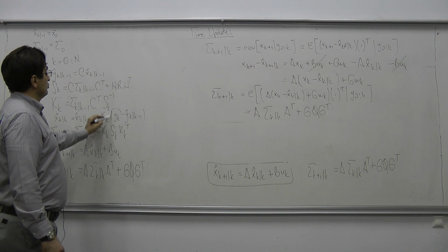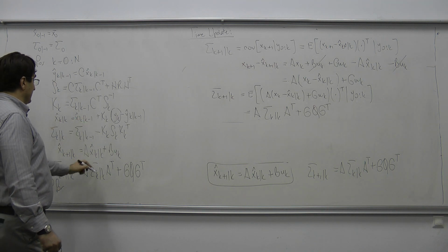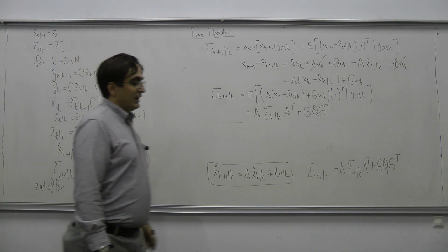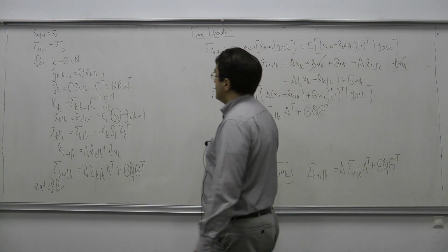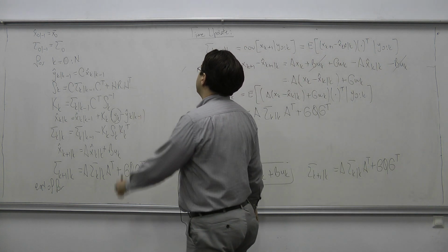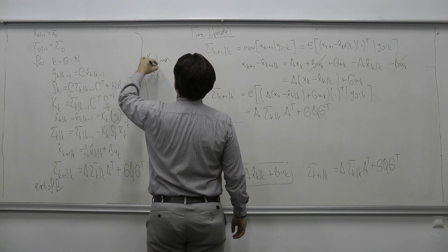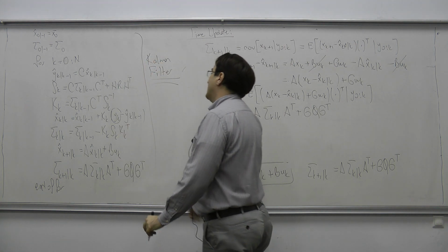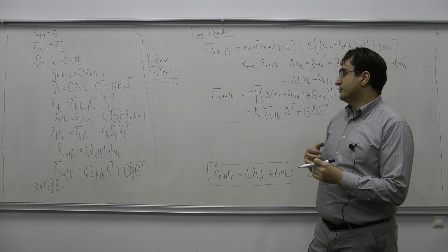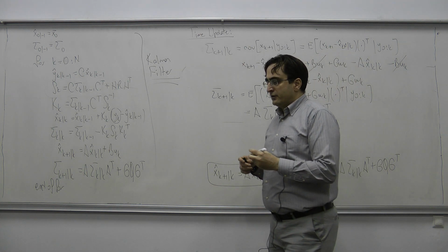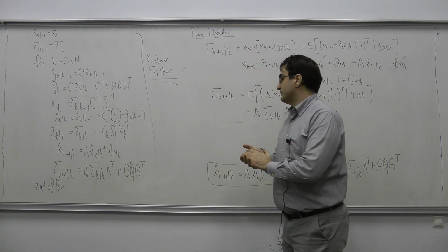So we see that we need to use these measurements to correct our estimates, and we see the covariance decrease and increase in both parts. We are hoping that we have something called observability, so that the covariances do not diverge indefinitely, and we get this algorithm. This algorithm is called the Kalman filter. And you see that it contains two parts, state update parts and covariance update parts. In the next lecture, we're going to start investigating the properties of this algorithm.